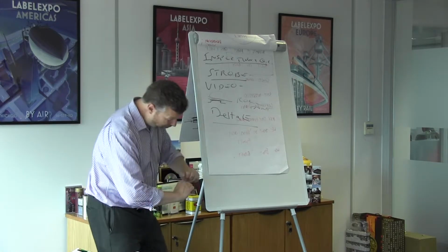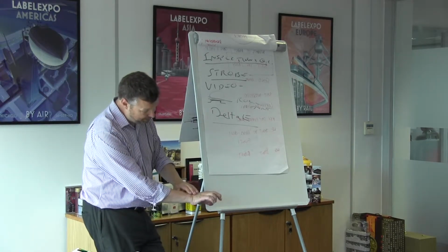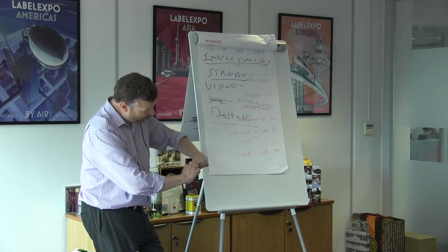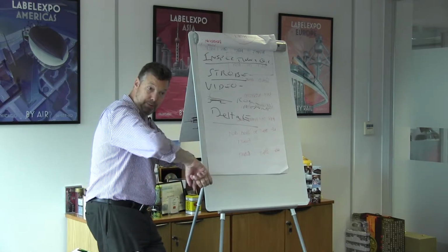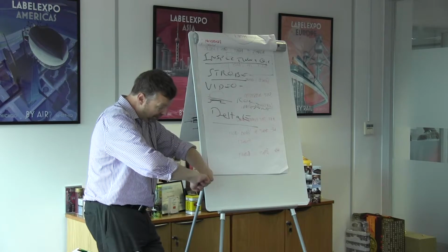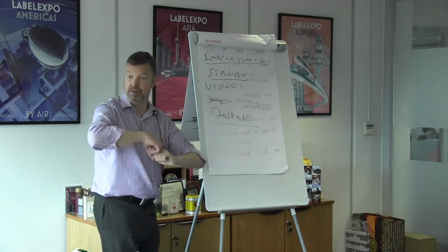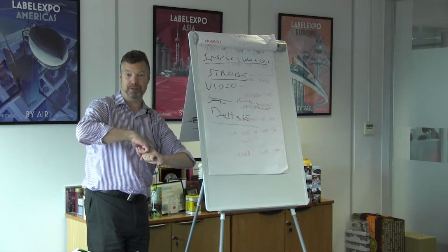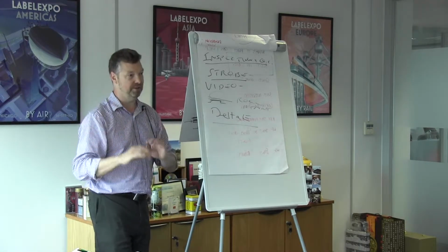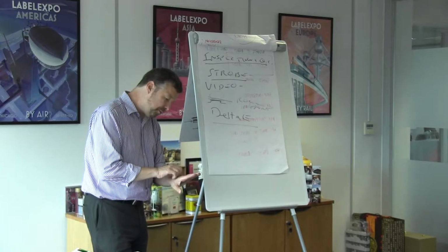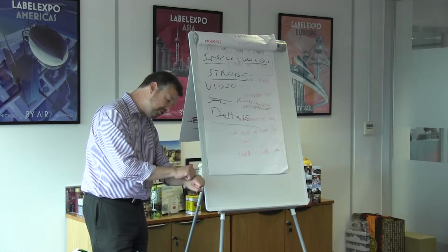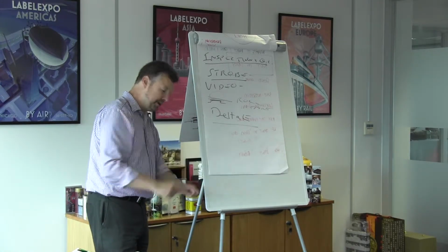We said that the real problem is that you've got a soft plate with the image standing up off it. You're rolling that onto the paper or the film, and if you have too much pressure there, it's going to squash. Okay, so you've got too much black now. You've got too much cyan. You've got too much, so the whole thing's finished. So you have what you just call a kiss touch. You touch it just enough. It just transfers the image.